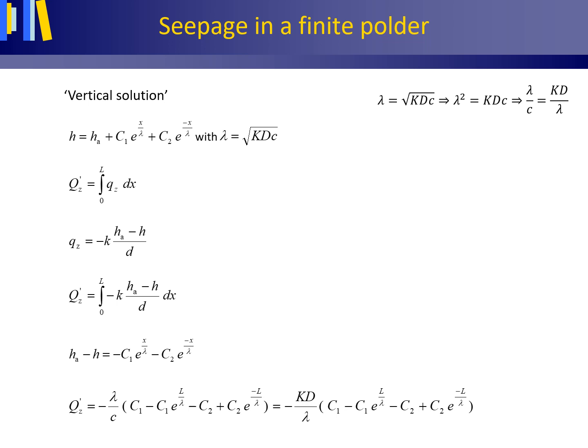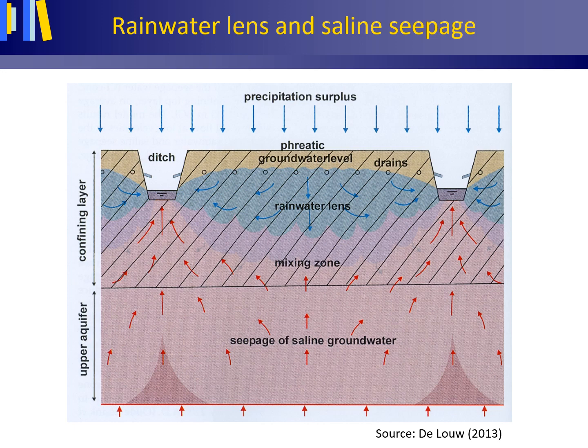When solving the upcoming leaky aquifer exercises, as mentioned earlier, always start off with the correct Laplacian equation as given in table 3.3. So that's this equation with C1 and C2 still to be determined. Analytical solutions to groundwater flow problems are especially useful as they provide a quick first estimate to many groundwater flow problems. But always be aware that in practice there may be complicating factors, as for instance is evident from this